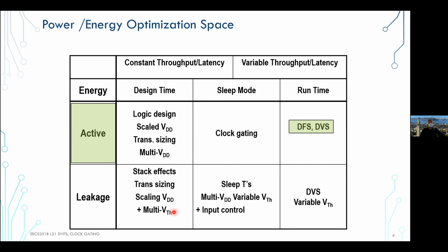And then, of course, next lecture, we're also going to talk about things like multiple thresholds. How do you create a design where you can not only optimize the leakage, but actually optimize the balance between dynamic power and leakage in the system? Because adjusting the threshold doesn't just adjust the leakage, it also gives you more headroom so that you can more efficiently use some of these dynamic techniques or even sizing techniques to optimize.